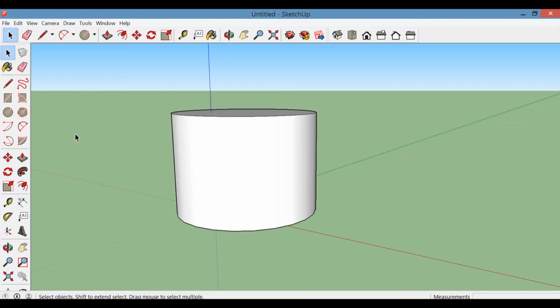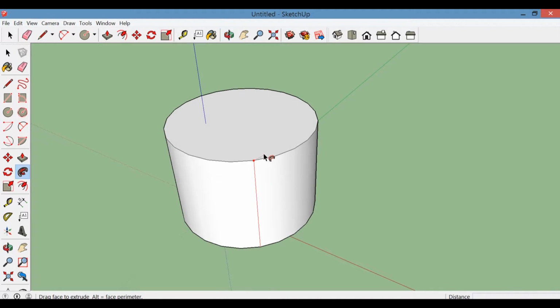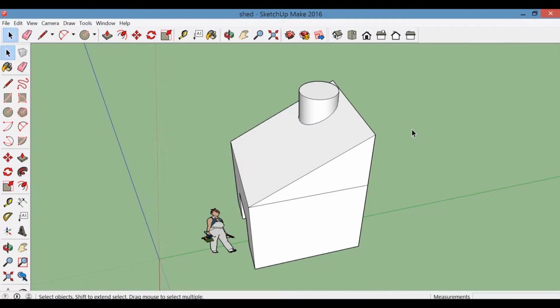But as you learn more of these tools and want to know if there are options to change dimensions, activate the tool and check to see if the blank white box on the lower right corner of the screen becomes active. SketchUp will usually tell you which quantity it wants you to specify right beside the box. For example, it might say length, or radius, or angle, or scale, and as you're using any tool, just type in your desired dimension and hit enter. There will never be a need to mouse click on the white box.